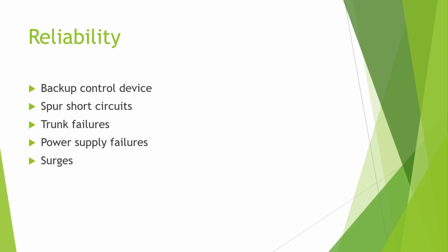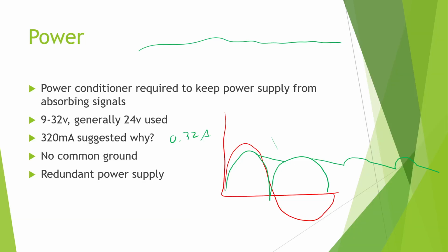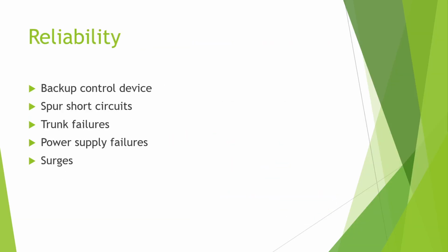That could be built into those lovely junction boxes that we saw a few slides ago, right here. You could have a little limiting resistor basically on every one of these spur boxes, so that way you are protecting against that possible downtime crashing the whole network. Also, depending on how your power supply is built, if you have a short circuit, that could destroy your power supply.